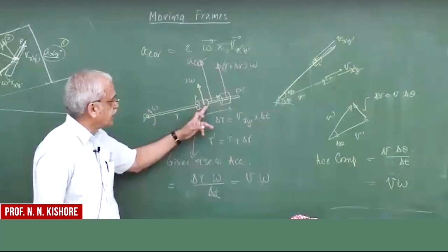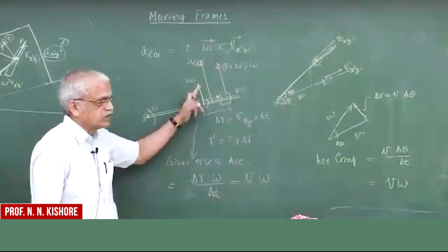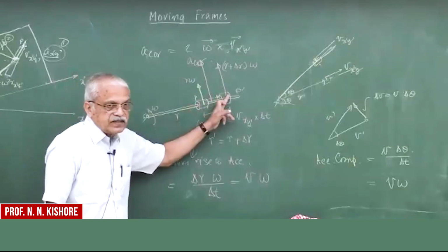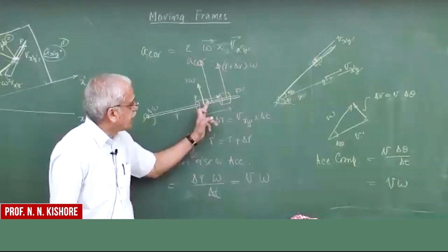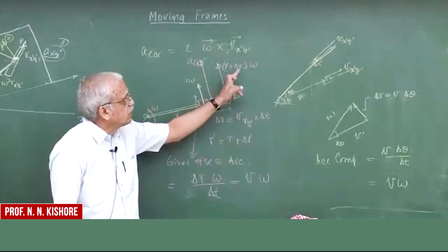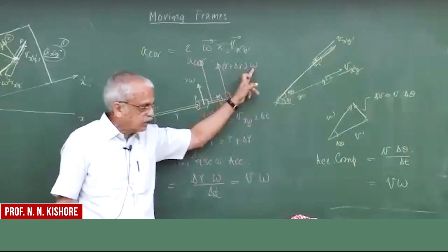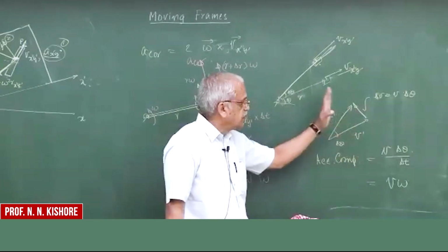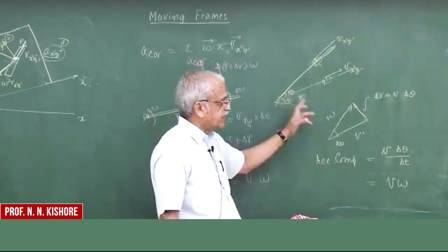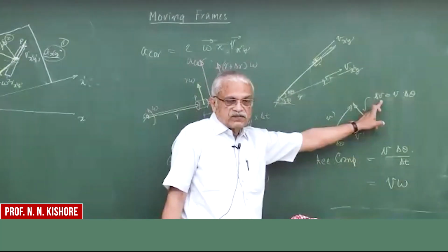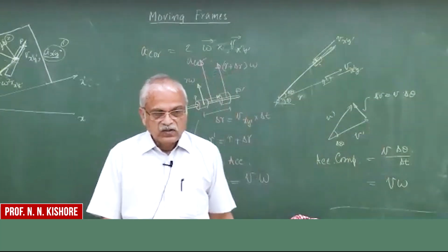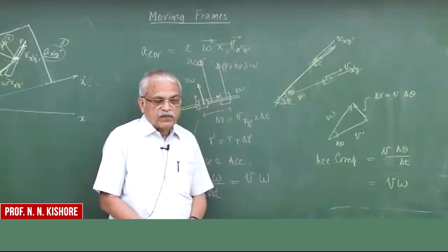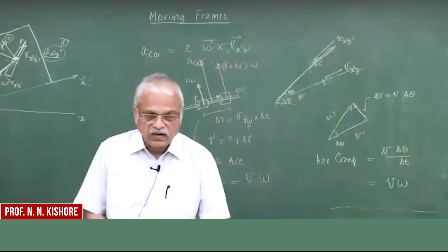The first component is r omega, the tangential velocity, which is increasing when the radial distance is changing to a higher value. That's number one. The other one is the velocity v. Since it is changing its direction by a delta theta, that also gives rise to an acceleration component. So these are the two components which form the Coriolis term, 2 omega cross v.